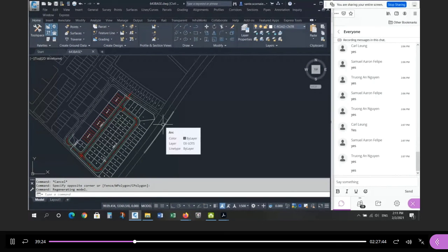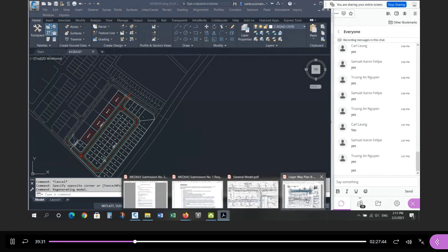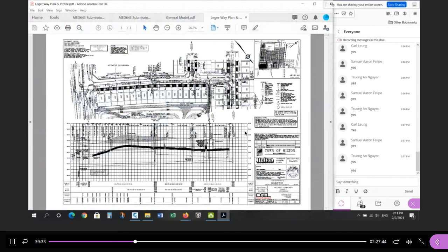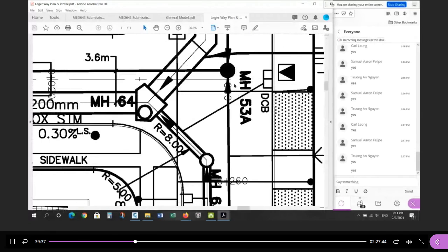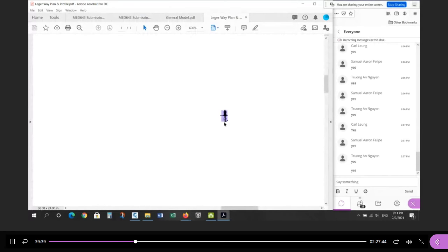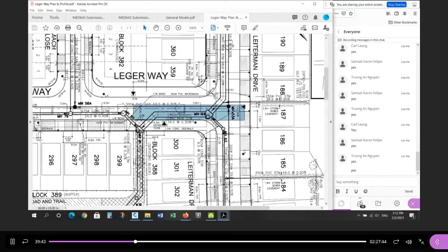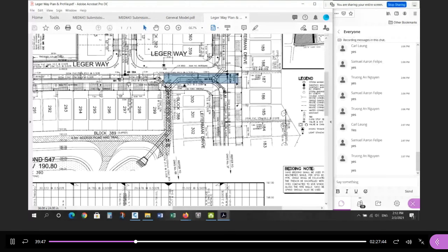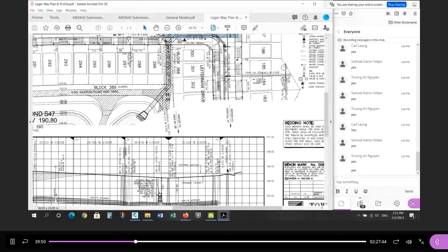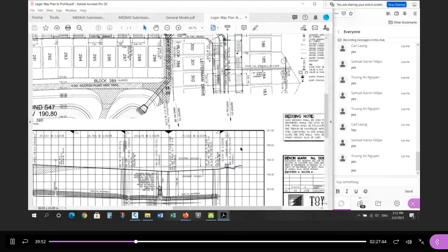Horizontal, vertical, and cross-section. Now, the nice thing is, because the design exists, I can use the PDF of the profile, and let's look at it. Right, here's the profile. The center line alignment, I'm going to zoom in here. It's hard to see. This is 0. So where the two center lines cross for this road and Ledger Way, that's 0. So there's a little bit of negative change here. The profile is consistent. 0 is exactly where the crown of the intersecting road is.